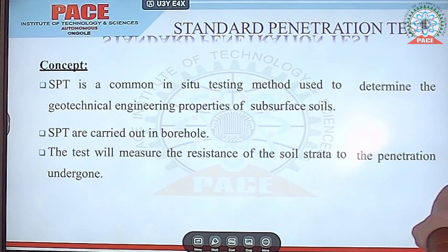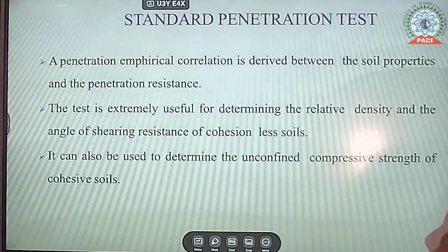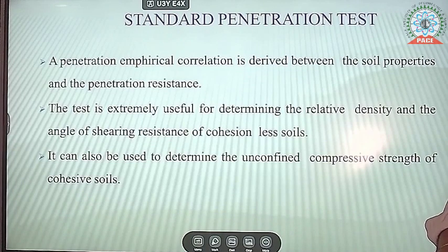The SPT is carried out in boreholes. The test measures the resistance of the soil strata to the penetration undergone. So in this one, we measure the resistance to the penetration. Empirical correlations are derived between the soil properties and the penetration resistance.